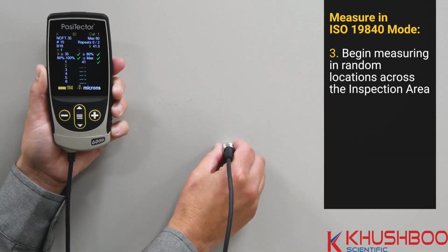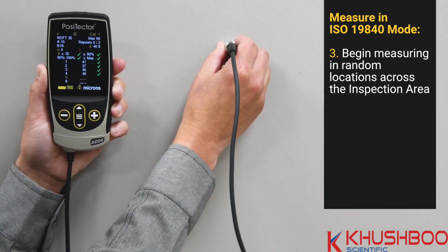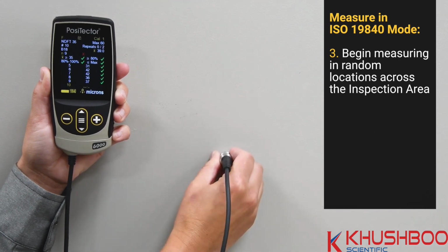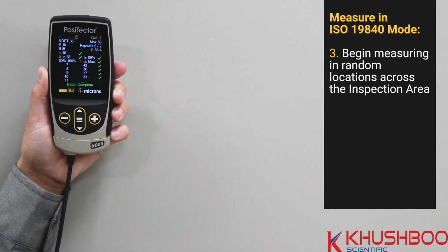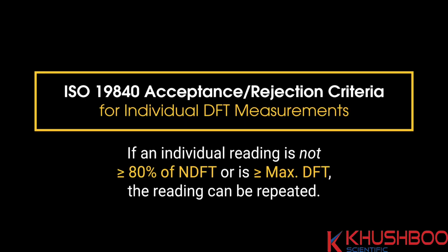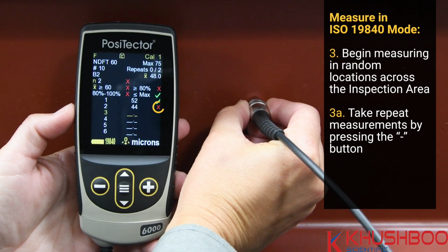Begin measuring, taking as many readings as specified in the sampling plan for the particular inspection area. Per ISO 19840, measurements are to be taken randomly across the surface. A checkmark or X will indicate whether the individual measurements passed or failed based on batch specifications. If an individual measurement is not equal to or greater than 80% of the NDFT, or is greater than or equal to the maximum specified DFT, the reading can be repeated by pressing the minus button.